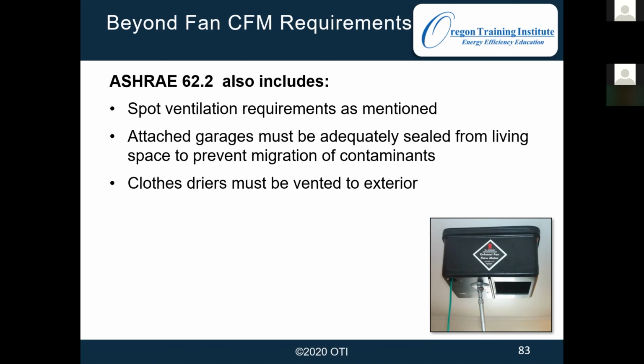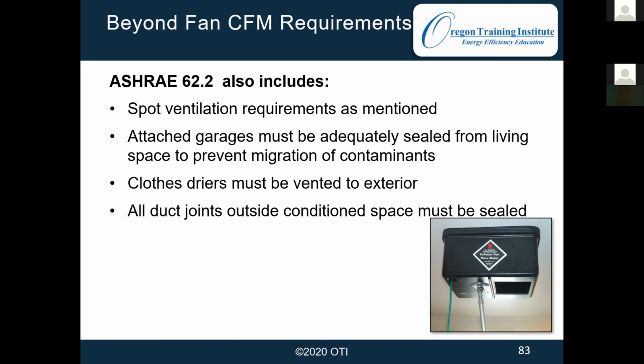Clothes dryer has to be vented to the outside. That's a requirement. The ducts are going to need to be sealed when they're outside the conditioned space. That's a requirement too. Regardless of whether it's cost effective, ASHRAE doesn't have that sort of requirement. It just states that this is what you need to do to meet these requirements of ASHRAE 62.2. So you've got to seal the ducts.